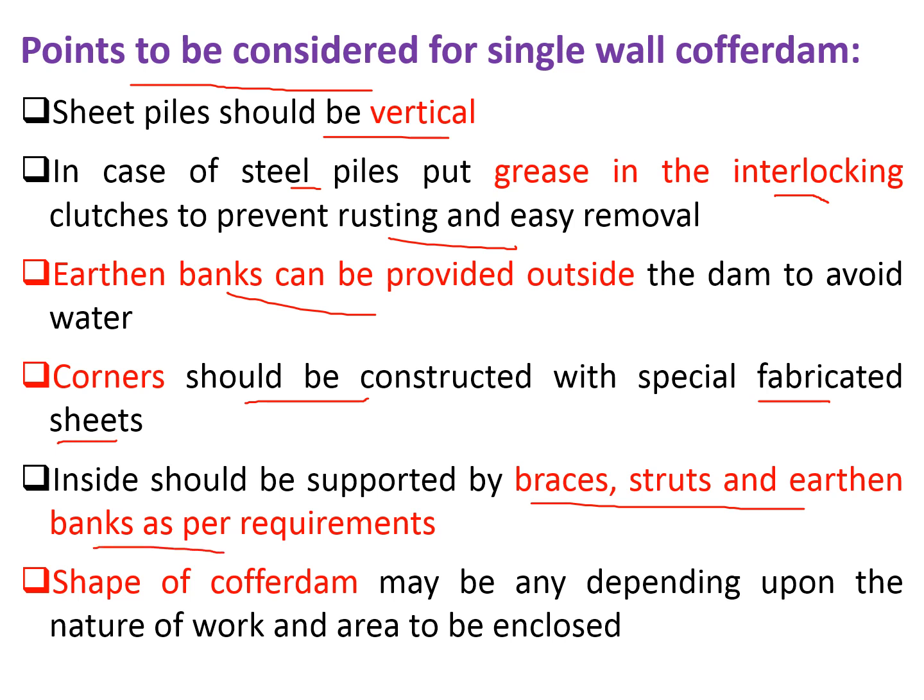So already I have told you: guide pile, then wales, then sheet pile, then again wales and struts. Then the shape of the cofferdam may depend upon the nature of work and the area to be enclosed. It is not always a rectangle, it may take any shape.